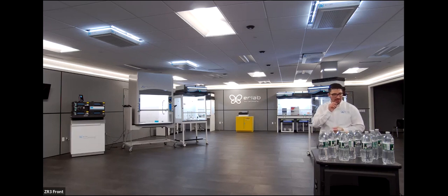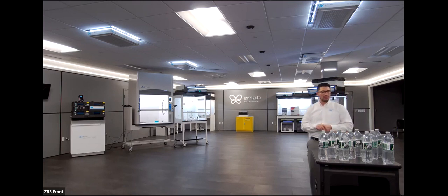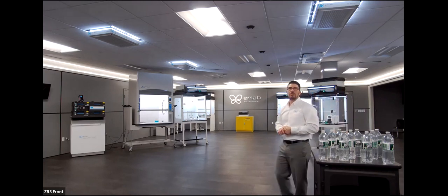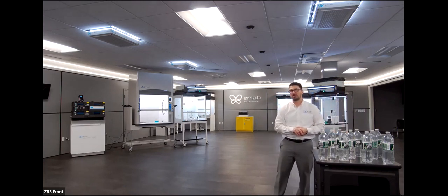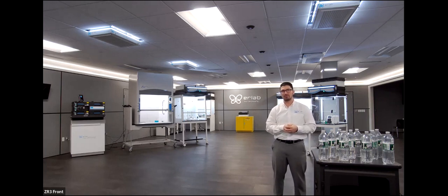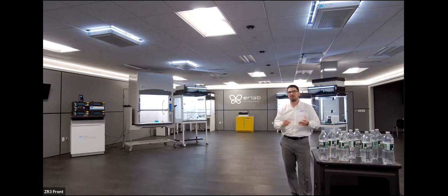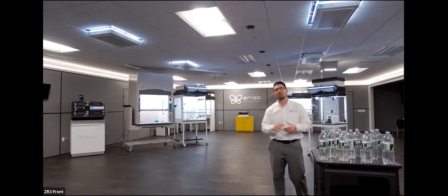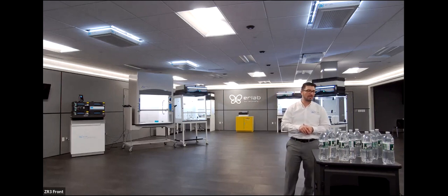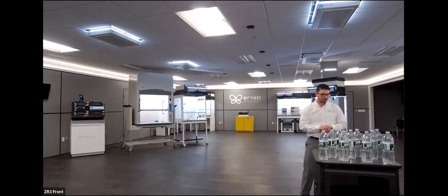Installation. How are the Halos installed? Great question. So very much like a lighting fixture. They're tied into the building's electrical. They're hung with either a threaded rod or gripple wire, and they're tied into the electrical circuits. Runs on 50 watts of energy, half of an amp, draws very little power. So yeah, an electrician would have to install it, but extremely easy to install.